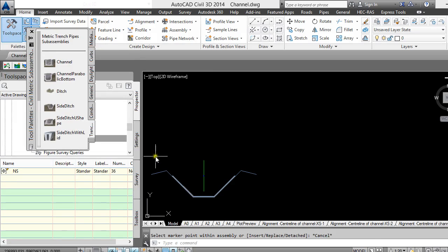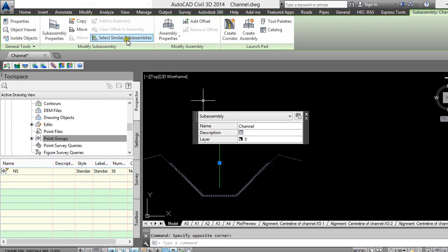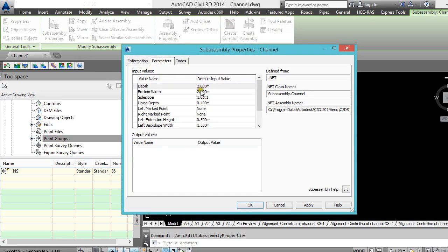Well, I want that to be 0.45 below the ground level. I don't want any lining. It's up to you how you're gonna change everything. I just simply need a trapezium underneath the channel. This is a small channel, 2.45 depth, 2 meter width, 2 in 1 side slope, and always click the help as needed.